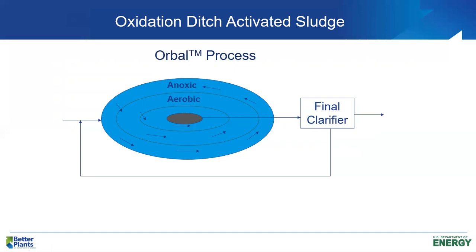We know that the nitrifying bacteria are obligate aerobes, but even at 0.1 milligrams per liter, they can nitrify. The nitrification rate will be slower, but we've got a fairly long hydraulic detention time. And when the DO is less than 0.3 milligrams per liter, we can also denitrify.